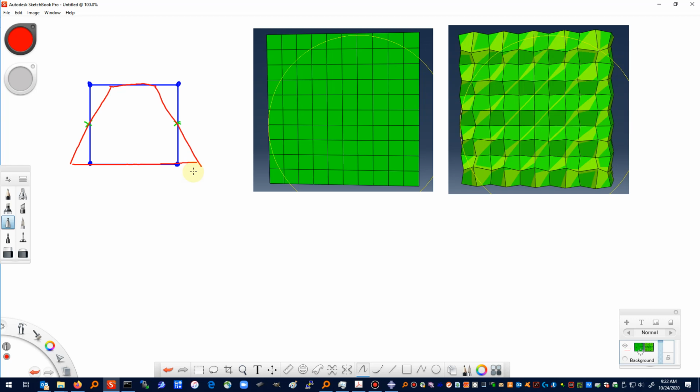Now, you don't always see this in your analysis if you're using reduced integration elements. In fact, it's very rare. I've been looking for a good test case to show hourglassing for a while and haven't been able to force one to happen until now. And so this is an interesting case for me. So again, what I've drawn is like one of these elements down here, but you can see the general type of what we call the hourglassing that's going on with those 2 elements.